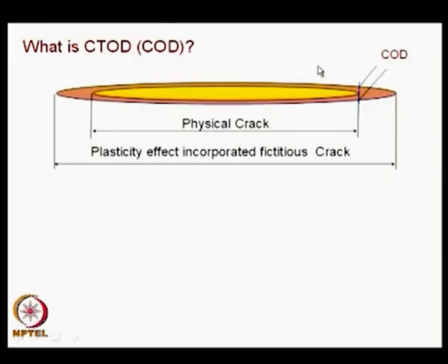We had looked at in linear elastic fracture mechanics. In EPFM, they use CTOD or COD, and this definition is taken from your plasticity enhanced crack tip. So, this is the fictitious crack and this is the actual crack, and whatever the opening here is known as CTOD or COD.